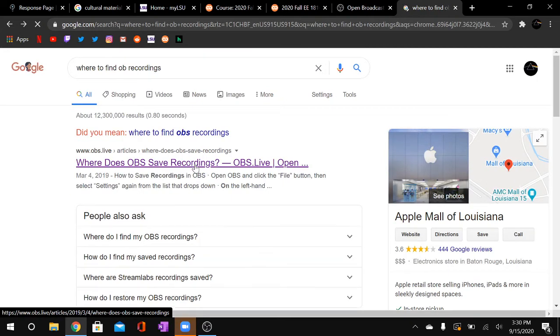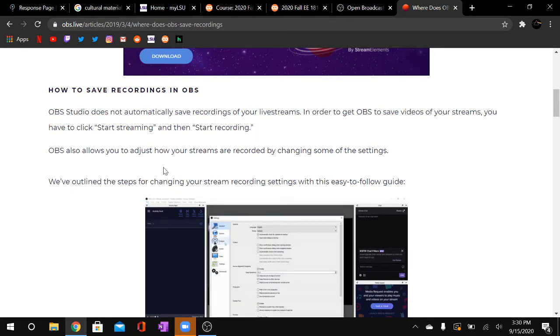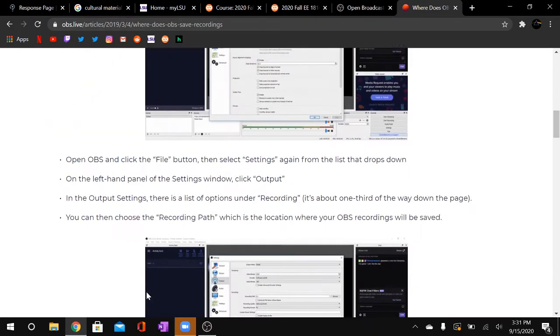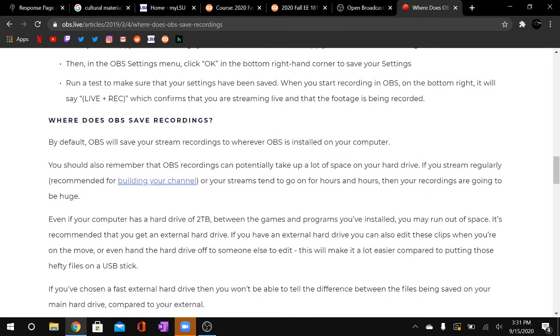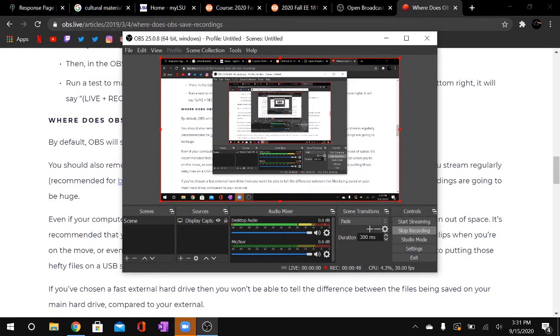connector that you're going to push carefully on the side of your MyDeck, because this black connector contains screws to hold the wire. So you push the stripped wire in it, then you turn the screw, and that will hold that connection properly, so it doesn't keep coming off and you lose signals.